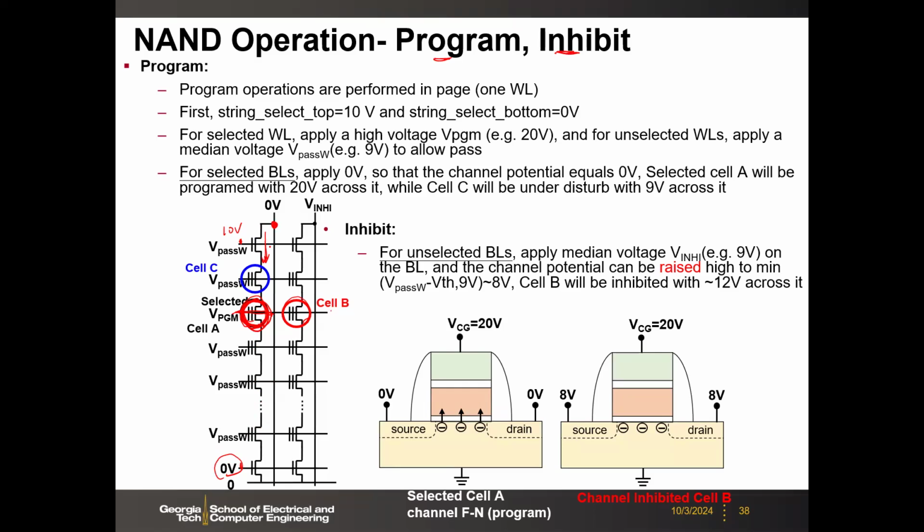So the essential goal is to deliver the voltage. If you look at a single transistor, the source side is floating, okay, right? Because here, if this is ground, then this is floating. For a transistor in this floating condition, this is very important: you need to deliver this voltage to the source side. Floating means this source side voltage can be any value, depending on what? Depending on how you apply the voltage to the gate and the drain. So what would be the source voltage here in this condition? The source voltage will be the minimum of VG minus VT, the threshold, compared to the VD.